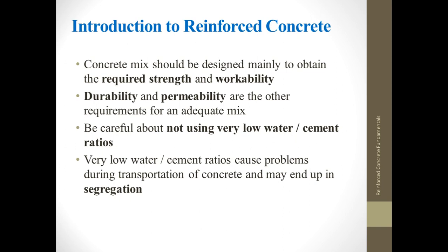And as I have mentioned, and this is one of the most important parts of the course, very low water to cement ratios cause problems during transportation of concrete, and you may end up with segregation. Segregation is a serious problem, and we must avoid it at all costs.